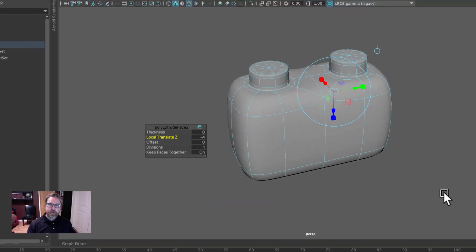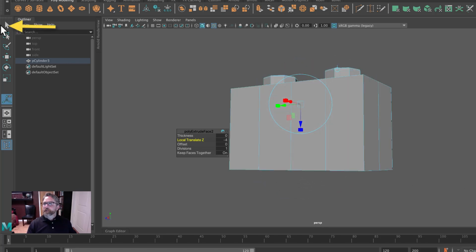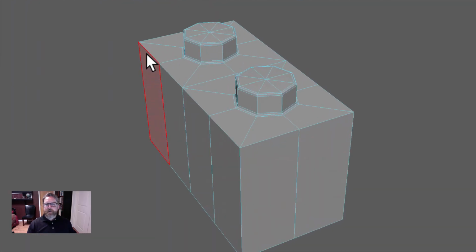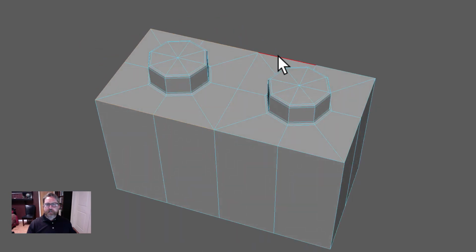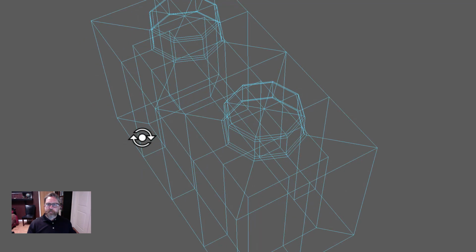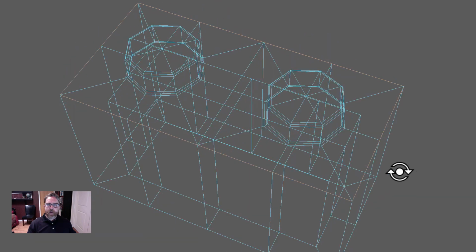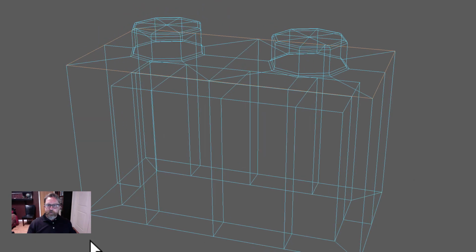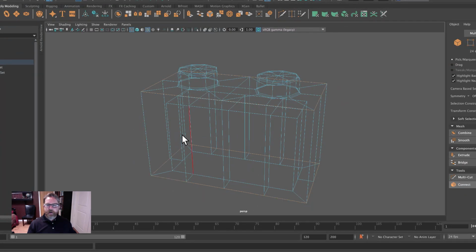Final thing to do, right, we hit the 3 key and we can see that that's soft all the way around. We'll need to make that selection. In this case, we're selecting rectangle, and we need to double click twice on that top one. I'll click off and do that again. So we're about to bevel. We double clicked, shift double click, so I have the top rectangle. We'll do the same down here. We'll shift double click. Now that gave us the entire rectangle at once.